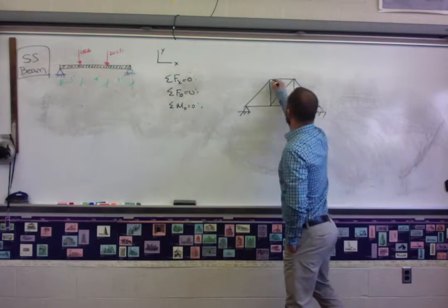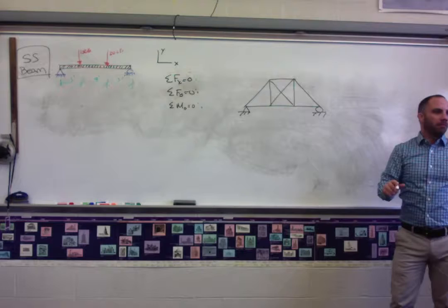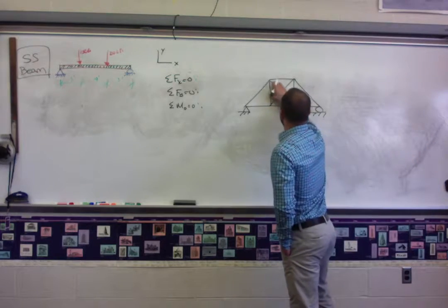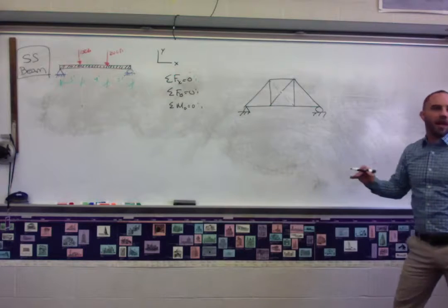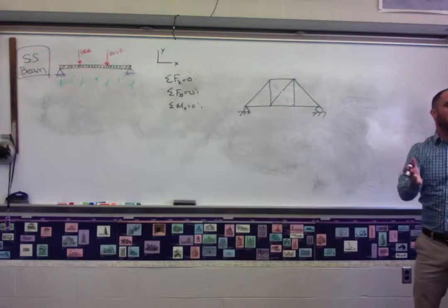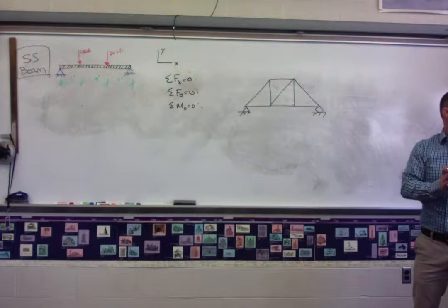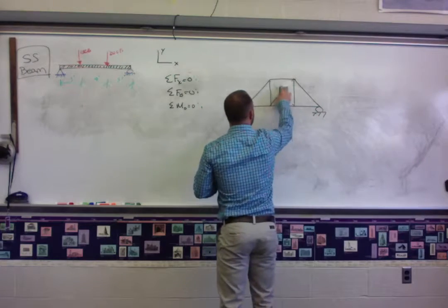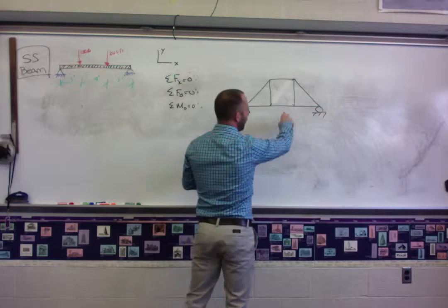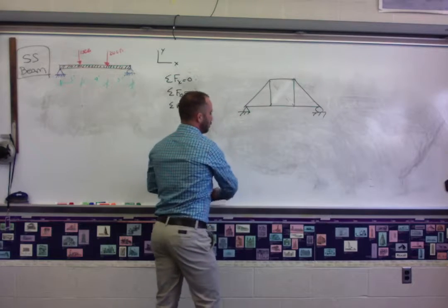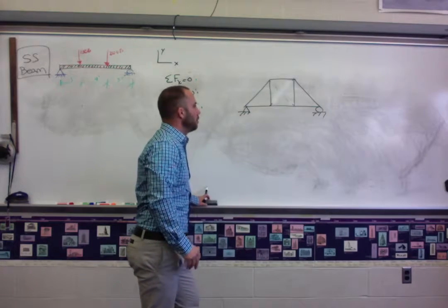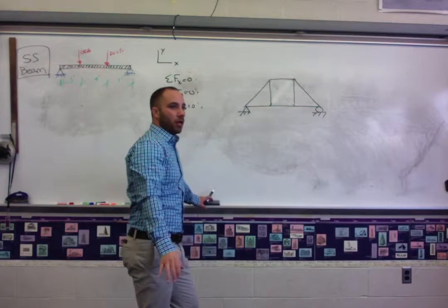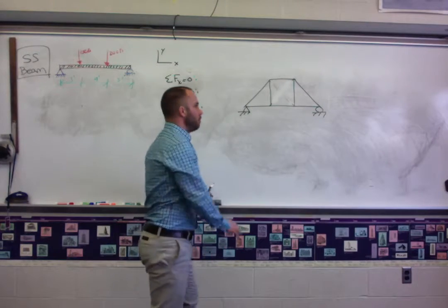Does it need this? Not necessarily. In theory, this is all it needs. One diagonal member to make it stable. The minute you take away a member, and I'll show you this on Wednesday, I don't think that is stable. That is also unstable. Yeah, you need to make sure that your trusses are stable before you analyze them.